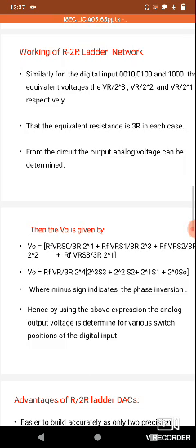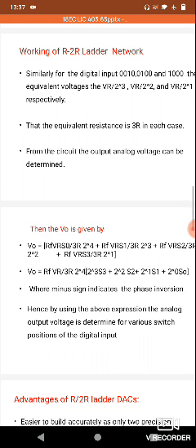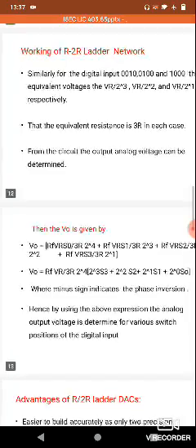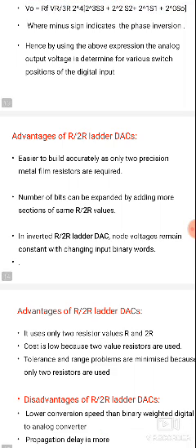Thevenin's theorem states that it is possible to simplify any linear circuit, no matter how complex, to an equivalent circuit with a single voltage source and a single resistance. That is, the total circuit is replaced by a single resistance and a single load. The total circuit is simplified by using the Thevenin's equivalent voltage and Thevenin's equivalent resistance.